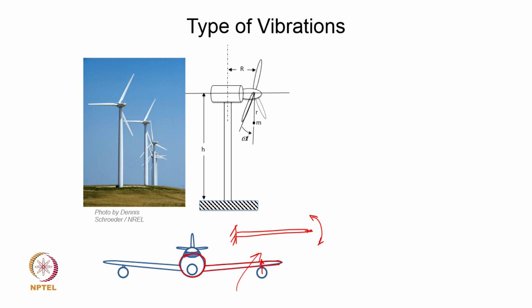Of course, the wings are not as simple as a constant cross section beam, but the cross section can have this kind of an aerofoil section, and then this cross section keeps changing along the length obviously. So, it becomes quite complex in that sense, but as a preliminary study one can estimate the natural frequencies of vibration for such a wing structure. Another interesting thing that can happen is that this wing, by its geometric properties and the excitation mechanism, will not only have the bending vibration, but will also have torsional vibrations.